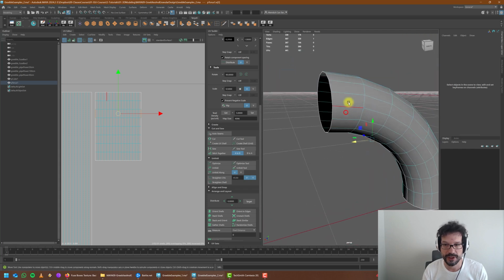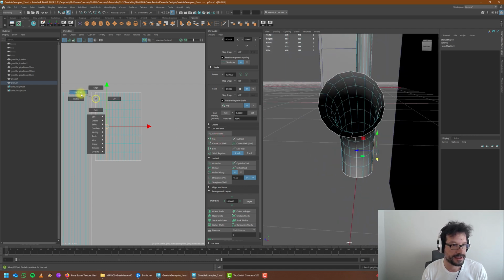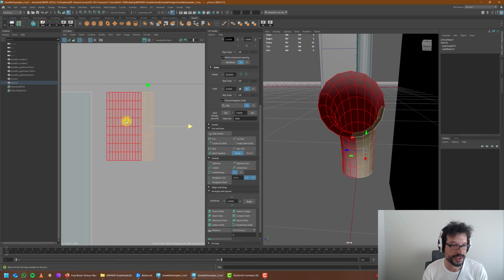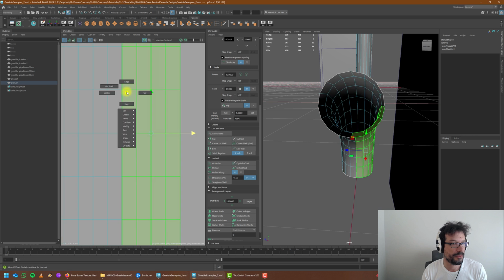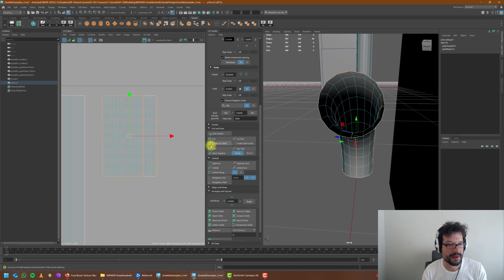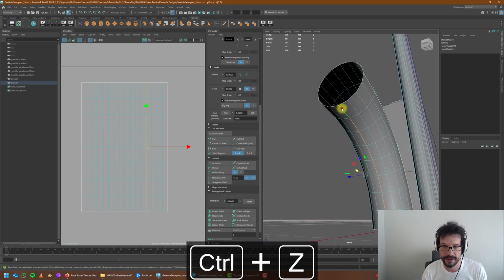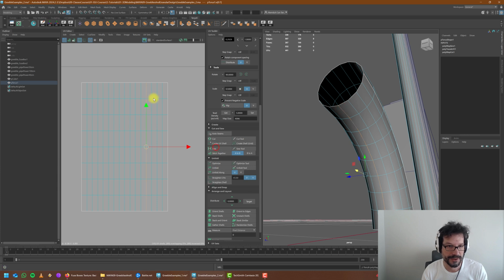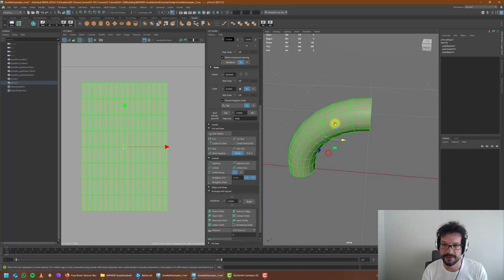I have to first break apart this object. Like, let's grab these edges, which I want them to be cut. Okay, then let's grab this UV shell, put it on the other side. Make sure these edges are the same edge. Check them. Okay, just get them as close as possible, because we don't want to move that edge whatsoever. Let's sew them. Okay, that doesn't work because I've selected from here, sew, and there you go. I have just changed the cut line of the object. You can do that like so.